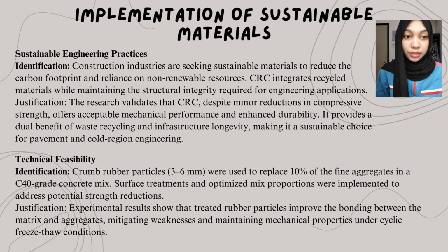For justification, the research validates that CRC, despite minor reductions in compressive strength, offers acceptable mechanical performance and hence durability. It provides a dual benefit of waste recycling and infrastructure longevity, making it a sustainable choice for pavement and cold region engineering.